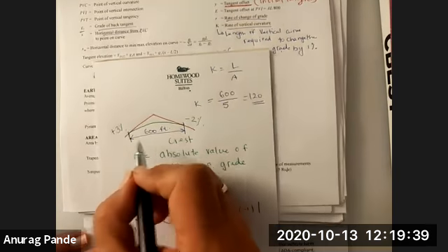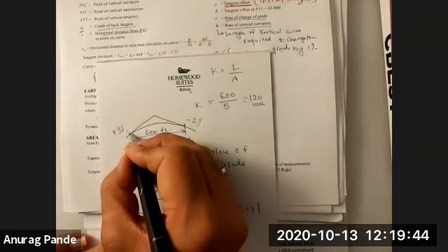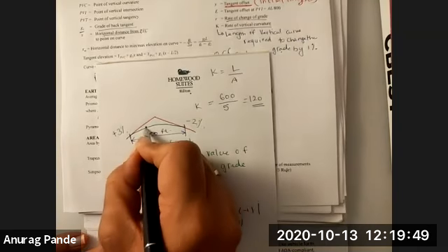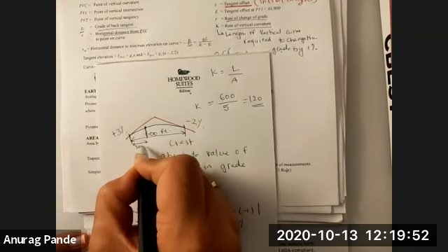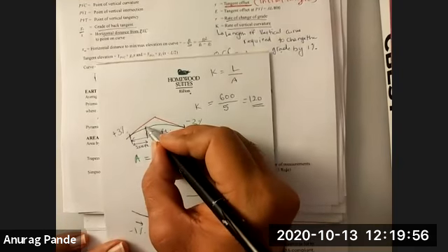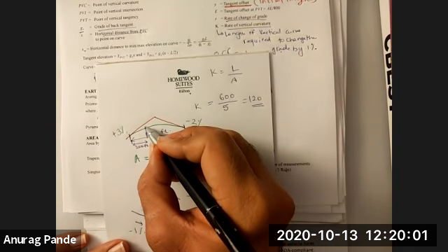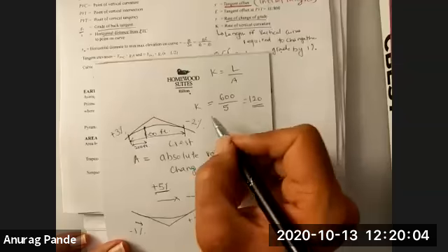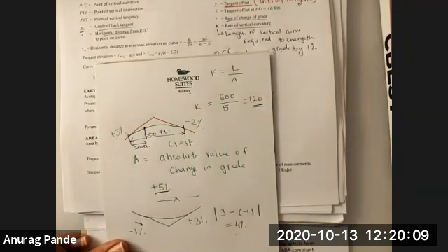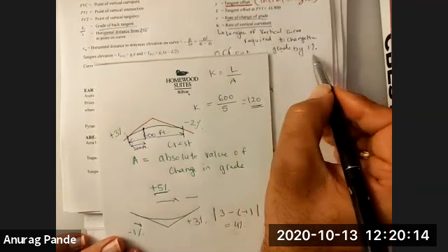So you can almost figure out, at any point on this curve, what the grade will be. Let's say you go 200 feet along this curve. What will be the slope of the tangent at this point? You can figure this out. How would you figure it out? You can say that the K value is 120 feet, which means the length of vertical curve required to change the grade by 1% is 120 feet.